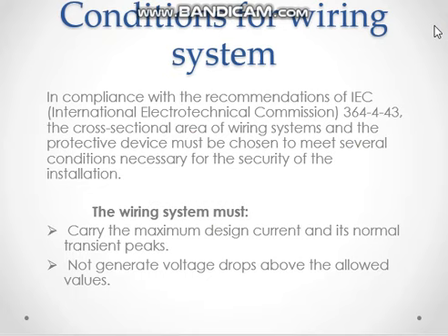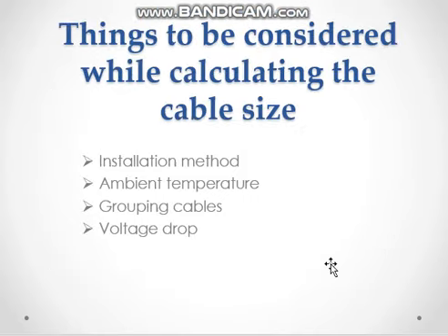So before we continue here, there are some conditions that you can check before calculating the cable size. The first one is to check whether your cable is able to carry the maximum design current and also its normal transient peak. The second one is that the cable you have chosen must not generate a voltage drop that is above the allowed values. Here are four things that you can check before